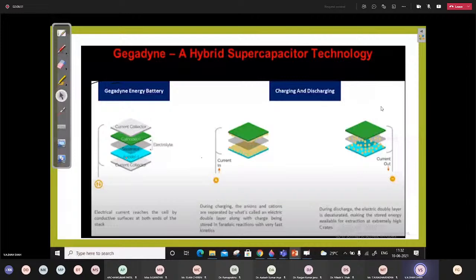So we have the rolling resistance force and the aerodynamic force. These are the two constant forces which the vehicle continuously demands when it is running on the road, whether in dynamic or steady state conditions. The grade resistance force applies whenever you are running your vehicle on a grade. And the acceleration force applies when you start your vehicle from zero speed. As all of you know, you have Crr times m times g, half rho A Cd times V squared, m g sin theta, and mass times acceleration.